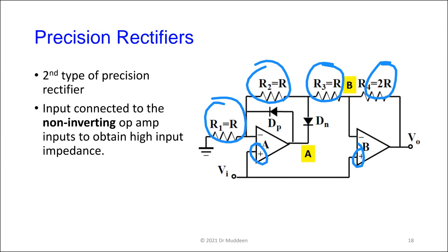If we have bias resistors around, they're normally a lot higher, and the input impedance of the op amp terminals is normally very high anyway. So we're going straight into a high impedance terminal. Some of this is back in your notes from 10, 11, so read it over when you listen to the lecture again, to refresh your mind on why I'm saying those things.